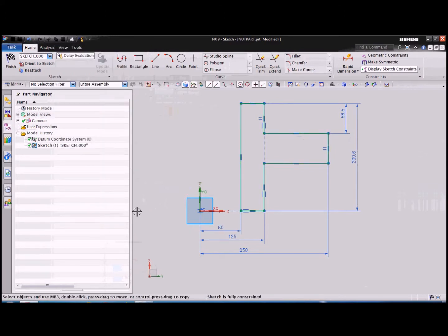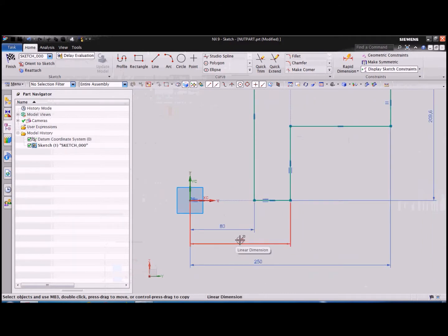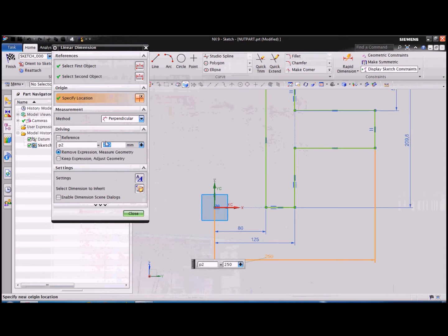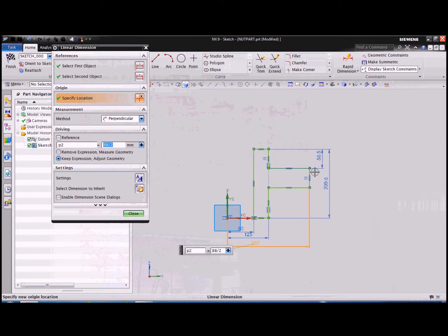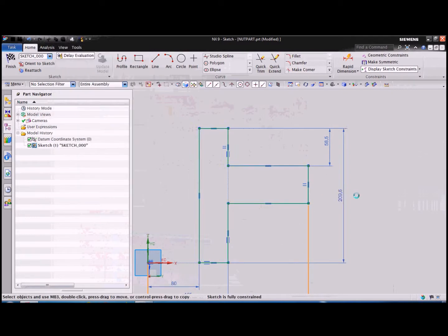At the starting of this video, I have calculated the values and now I am using all those values to create this part. So it is very necessary for us to read the drawing carefully so that you will understand in case of whole base system what we have to refer, and in case of shaft base system what we have to select.